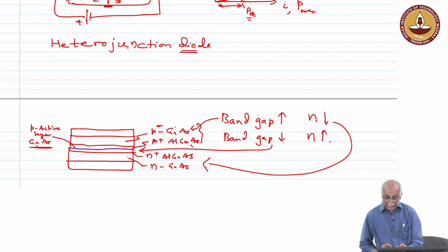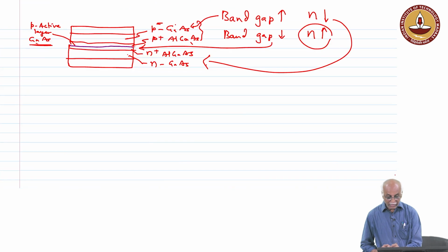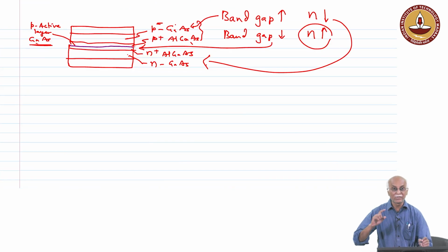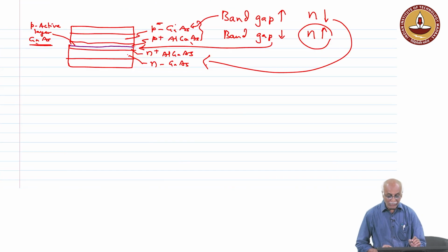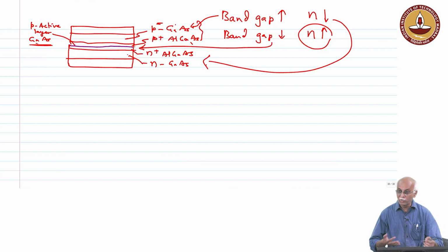Refractive index being slightly larger, we will see a waveguide effect, with core and clad combination coming into picture. What does it mean? More of the photons which are generated will remain confined within this region and will propagate along this line, like a waveguide or optical fiber.